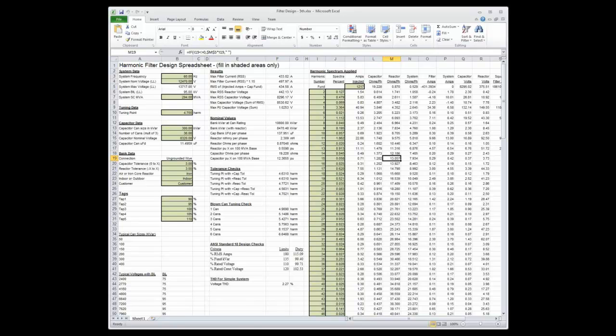So, have any of you seen filter capacitor banks where there's several stages, maybe hooked in a binary configuration, where you can throw some on and take some off so that you're matching power factor more closely? In those conditions, I have seen times where, for those type of arrangements, there's vacuum bottle failures. I think I've seen it mostly for just plain capacitors being applied on a bus.